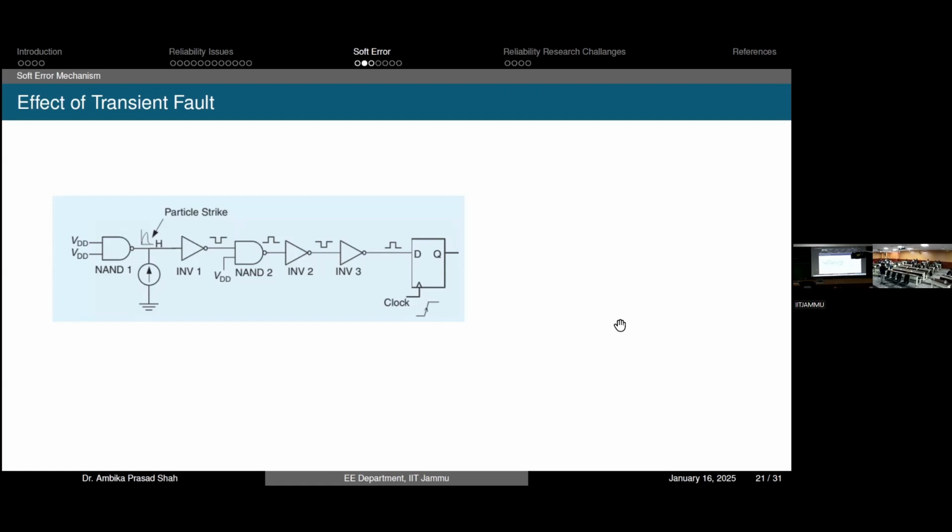And if it is considered as an impulse for that inverter, it will propagate that impulse, and from high it can generate a pulse like a low logic. Now the actual one I was expecting should be logic 1 always, but because of that spike, it has created a pulse, and that can be at logic 0. Now I will tell you why I have used the NAND gate over here. Let us directly come to this point. I will tell you what is happening over here later on, don't worry.